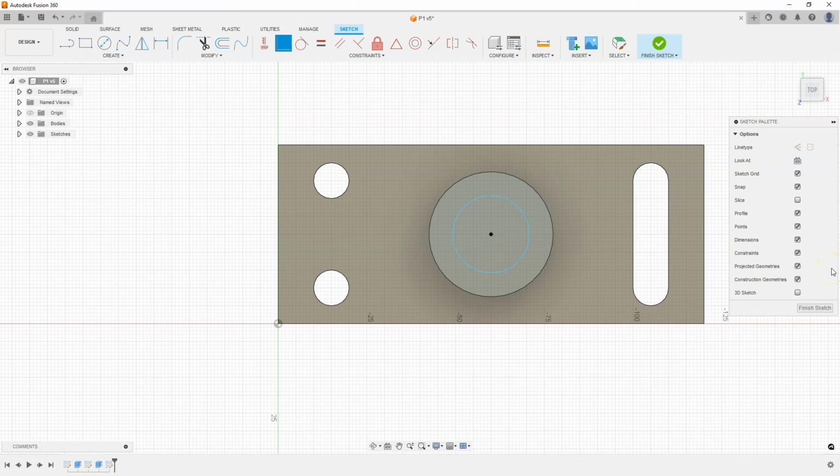When creating projects on your own, and as you gain experience, you will be able to assess in which situations it is better to add constraints manually and where to use automatic constraints. For me, one of the situations where I tend to use manual constraints is in projects where there are different geometry snaps close together. Then, to make sure I specify the constraints correctly, I first draw the geometry somewhere off to the side and then add the constraints manually.